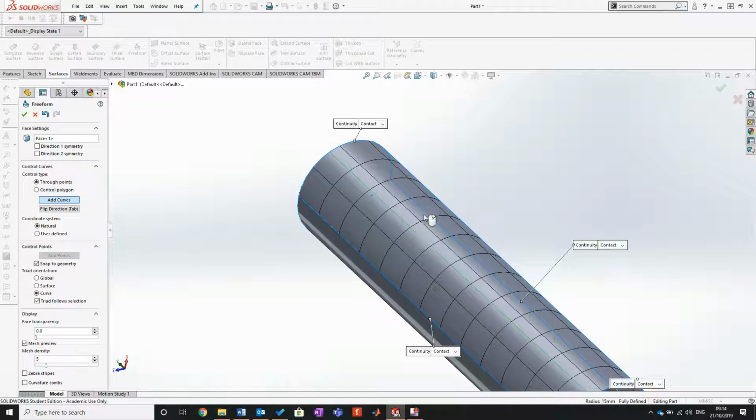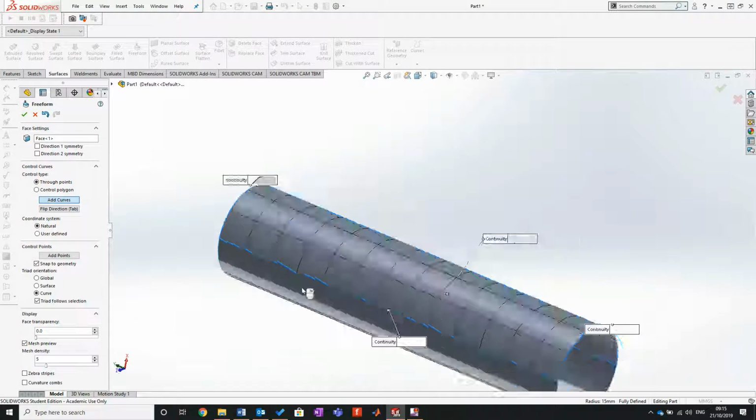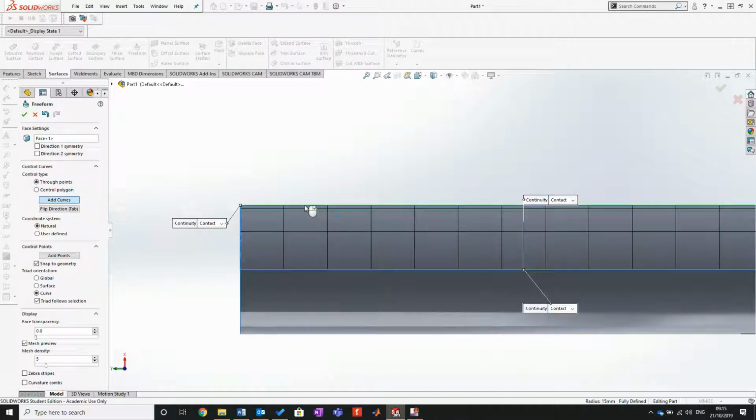So bring this across. I'm going to just roughly aim it around the midpoint there. Now I can add more curves, but for the nature of what we're making, I don't want to add more curves. I just want to keep it to this one. So I'm going to come from here and then come from the right plane. And I'm now going to right click. So now what that'll do is only trace against the curve that's present.